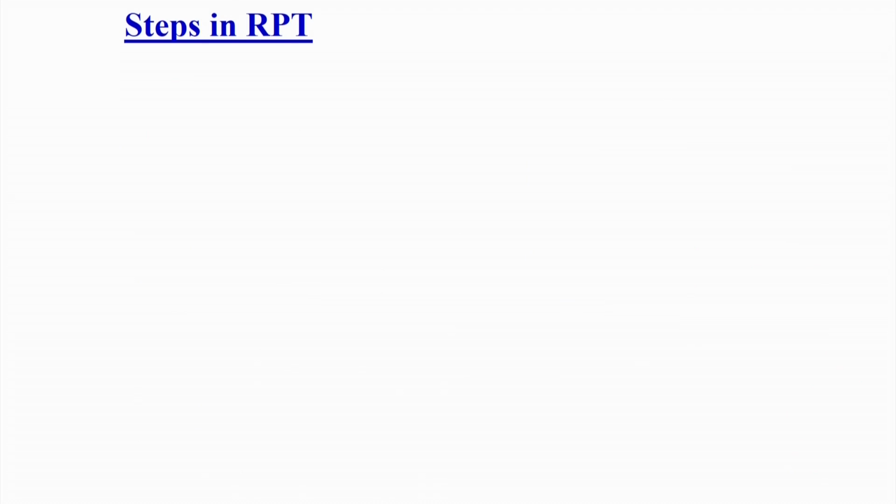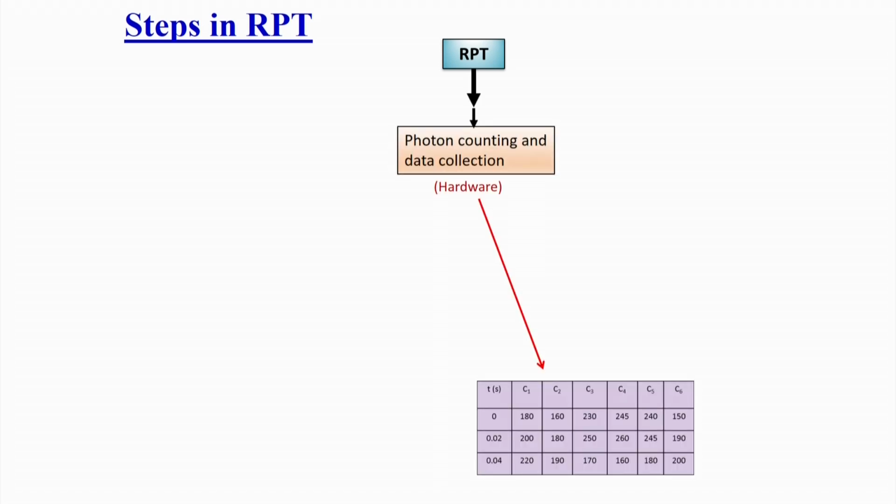Though, again I said, the technique looks very easy, it is not that simple, because RPT is a multi-step process, not a simple single-stage process. So, what are the stages involved in RPT? One stage is the experimental stage, where we keep the particle free inside the bed of interest and see how the particle motion is changing with time, or how the particle position is changing with time.